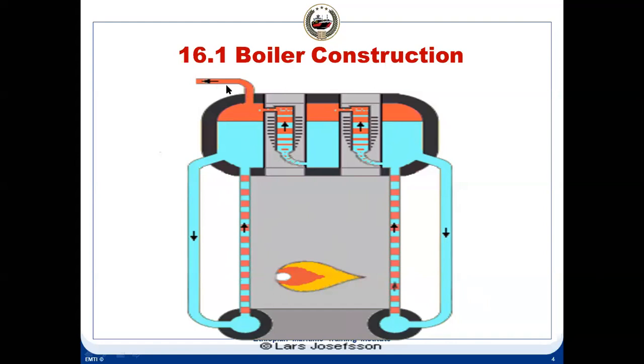From the steam drum, you have saturated steam going off to various services. But from your furnace, the smoke is passing through these bigger diameter tubes, smoke tubes, and going off to the funnel. And in these bigger diameter smoke tubes, what they have put is these are called pin tubes or sun rod tubes. That is the speciality of this design.